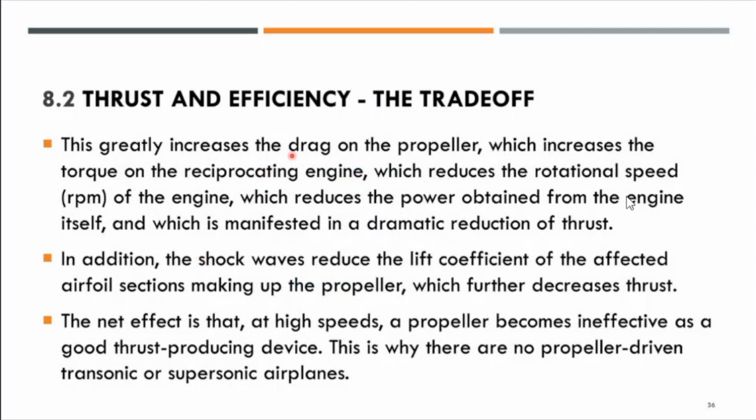When that happens, the drag on the propeller increases, which increases the torque on the reciprocating engine, which then reduces the rotational speed of the engine, which eventually reduces the power obtained from the engine itself, and is manifested in a dramatic reduction of thrust.